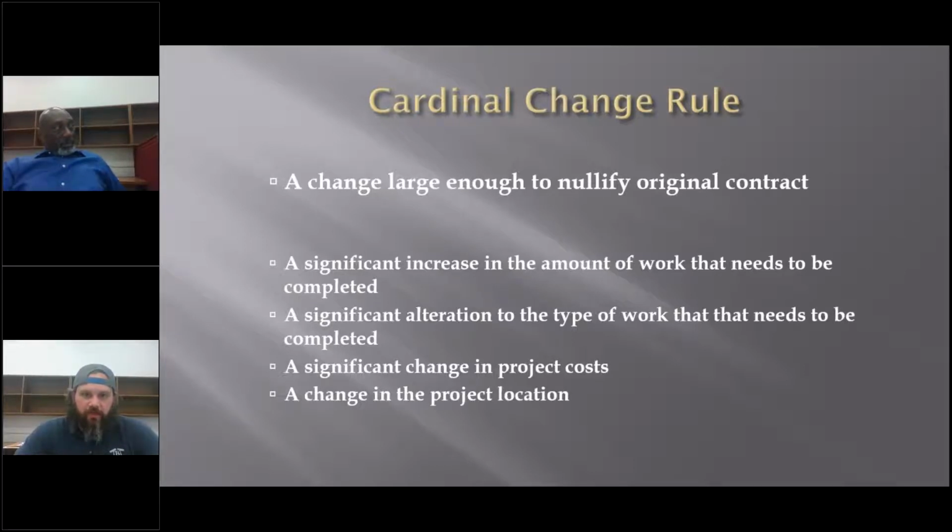A significant change in costs or the location. If I'm putting up a building in Cleveland and I have an agreed upon price for doing that, that same price or the same size building can't just be transplanted out to Toledo, Ohio, or Cincinnati or Columbus. For me, it's because of code and load issues with snow loads and wind loads, and every single project is extremely unique from that perspective.